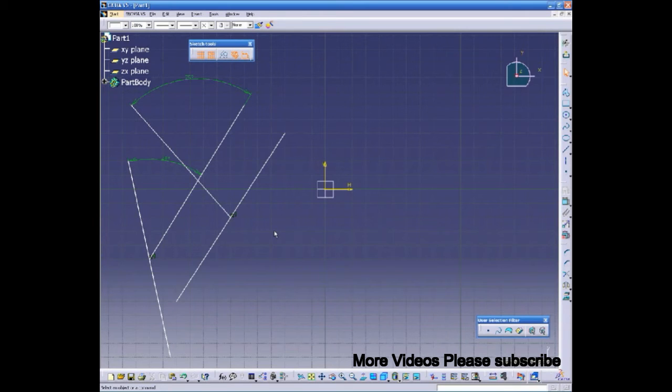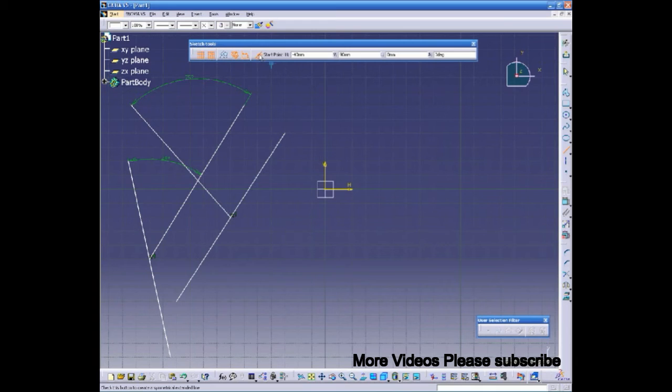OK then. Now, instead of the direct method, let's use the Sketch Tools toolbar to create line. Assume we need a line with length of 125 millimeters, that to be started from the point 10, 12 and has angle of 45 degrees with respect to the absolute system. OK then. Click the line icon and deactivate the Symmetrical Extension option.